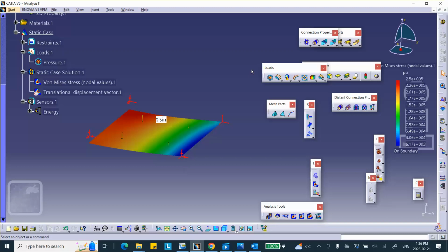Definitely, in all likelihood, unless it's a very unusual situation, very special type of heat-treated steel, this will definitely yield. The yield strength for structural steel is about 30,000 psi. This is 8 times bigger. Yep. Anyway, that takes care of the second activity.